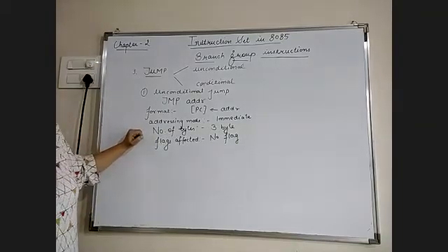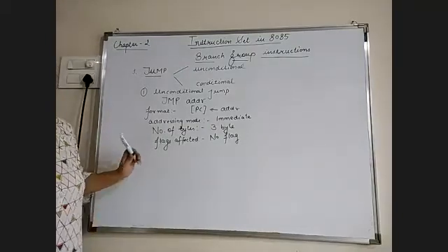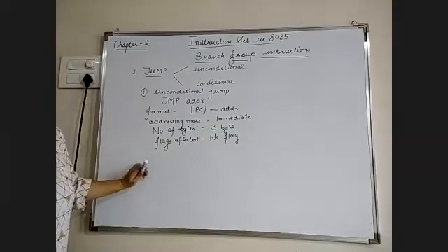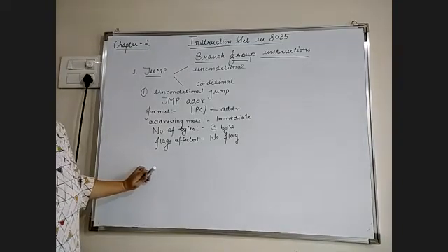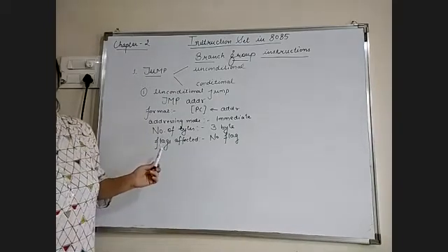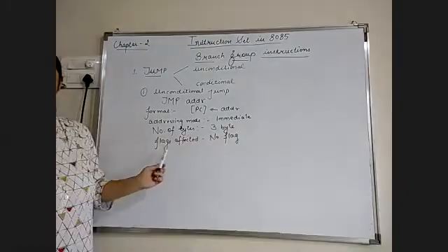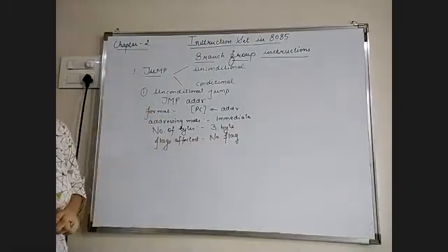We are not performing any arithmetic or logical operations. So if we are not performing any ALU operation, the flag register won't get modified, because we are simply changing the sequence of the program for execution. That's why no flag will be affected after the execution of the jump statement.